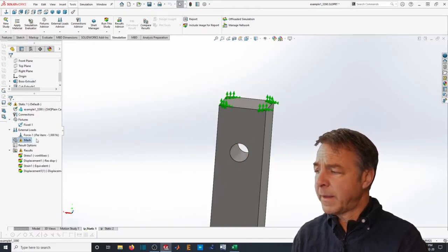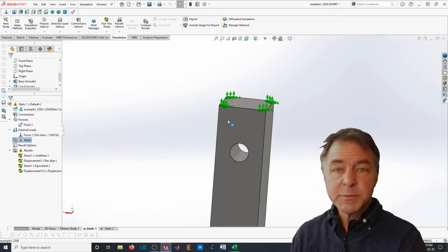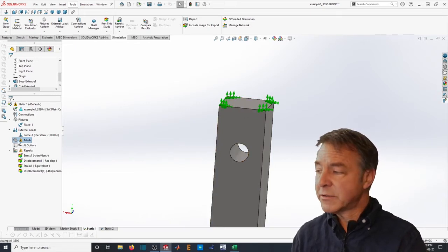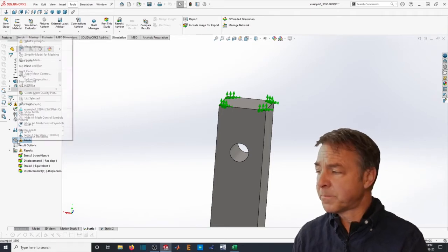And maybe I should consider that as being a better simulation, more realistic to what I'm looking for. So it looks like we've gotten into a bit of a problem where by adding a very small detail feature like a hole, we've actually found that the boundary condition that worked for the simple model doesn't work anymore.